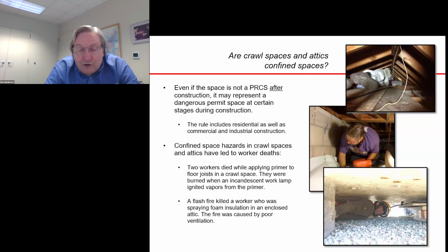So it could very well be a permit space on the day that the sealant is applied. A day later, after the sealant has completely dried, cured, and is no longer producing a detectable vapor, maybe it's not a permit space. It's still a confined space. The issue is, what do you have to do about it?